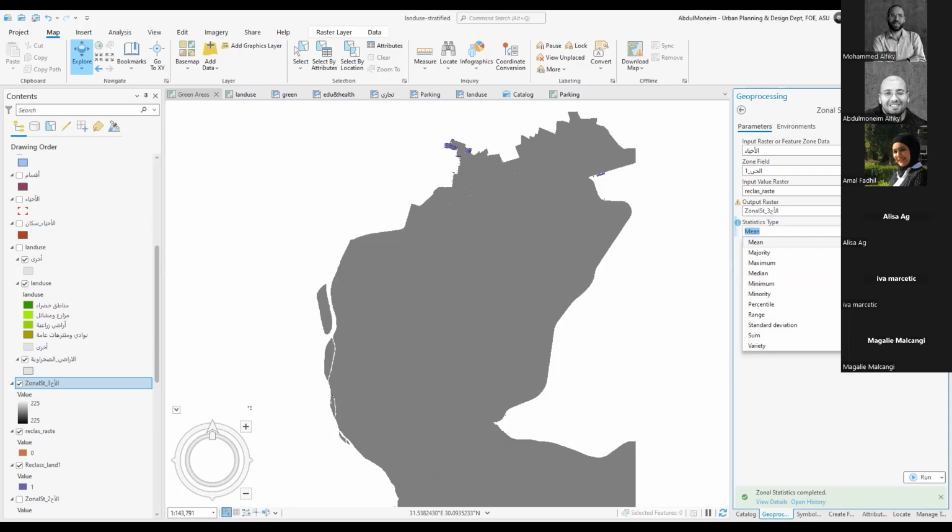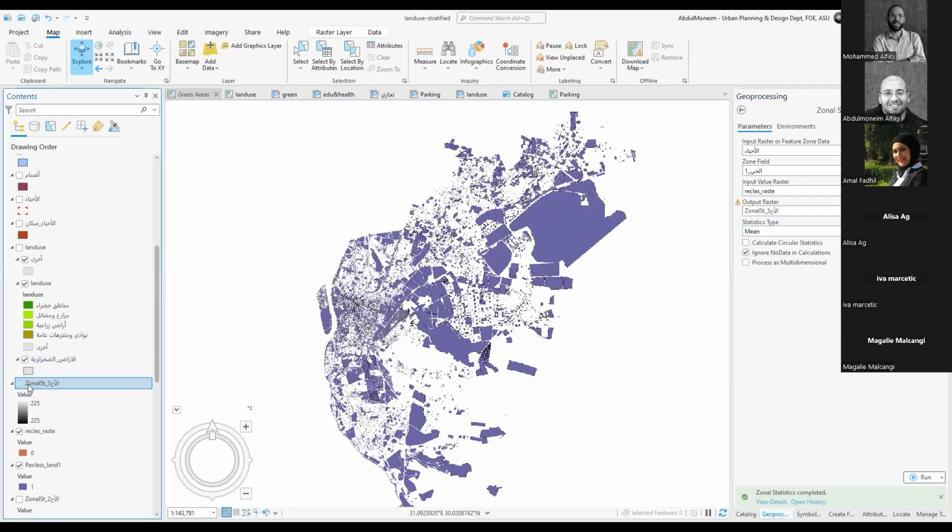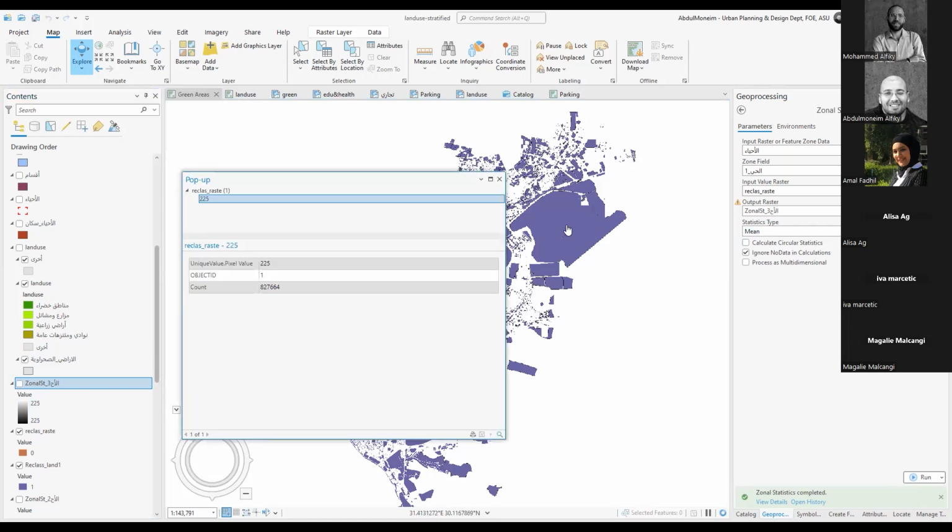Oh yeah, so this is how we have to normalize the data. Basically, each cell, this is why we got another phony result. I'll check how to fix that and come back to you. But basically what happened here, because each cell is 225 and we're asking for zonal statistics and calculating the mean, the mean in every location is 225. It's the average of the results. We have to combine all the results together and then run the zonal statistics. So we need an extra step.